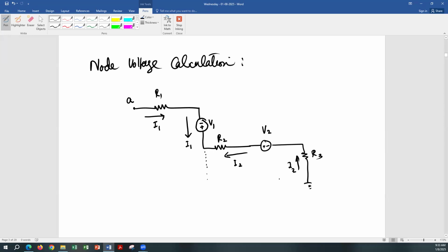In a circuit, you can calculate with your ammeter the current flowing through different branches, and you know the voltage values and all those things. And someone says, okay, well, you know all these values, how are you going to determine what is the voltage at node A? So how are you going to do that? Yes. First, you need to know for what? You choose a reference. What is the reference you're going to choose?